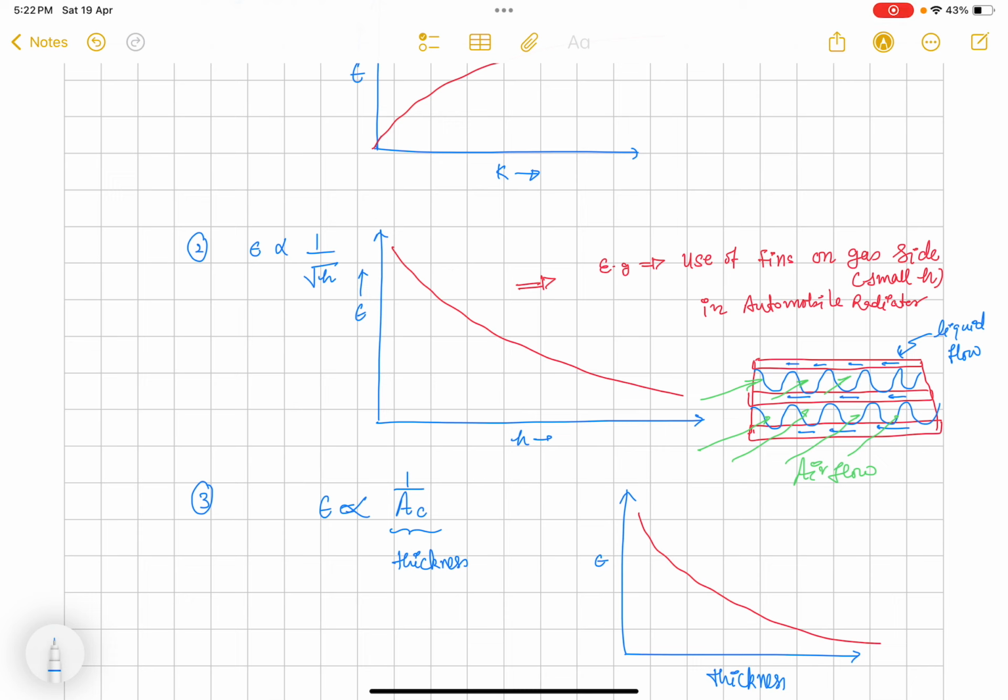All right. So fluid side thermal resistance we have defined as 1 by hA. So if h is low, thermal resistance will be high, right? So for example, fins are used in the automotive radiators on the air side, where air is blown, and coolant flows in the tubes, and outside we have the triangular kind of fins on the automotive radiator where air is flowing.